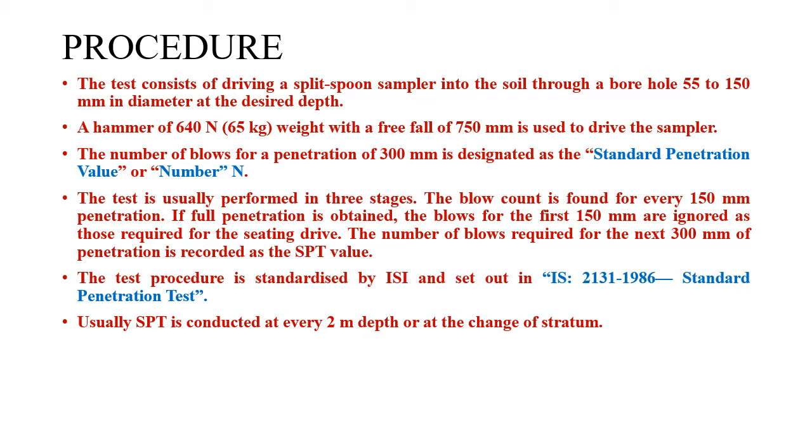Otherwise, another criterion is that you conduct the test at every 2 meters depth. This is a standardized procedure by the ISI, and you can find the details in IS 2131 1986, standard penetration test. So there is an IS code for this test as well.